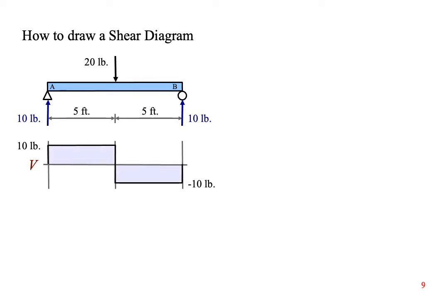It's easier to read a shear diagram if it's shaded in. It's a good idea to mark the values of the shear load on the shear diagram because it will make it easier to draw a moment diagram later.